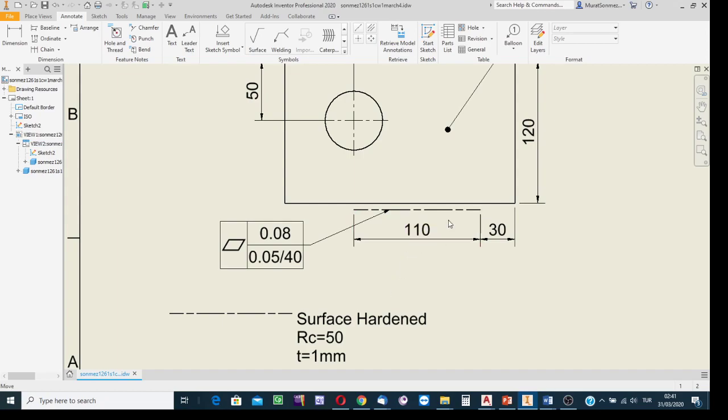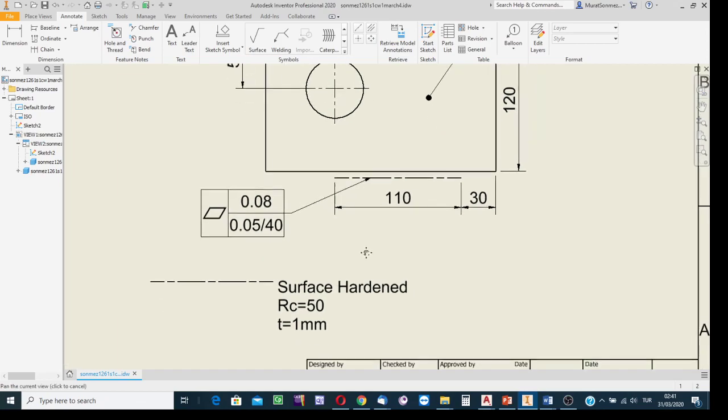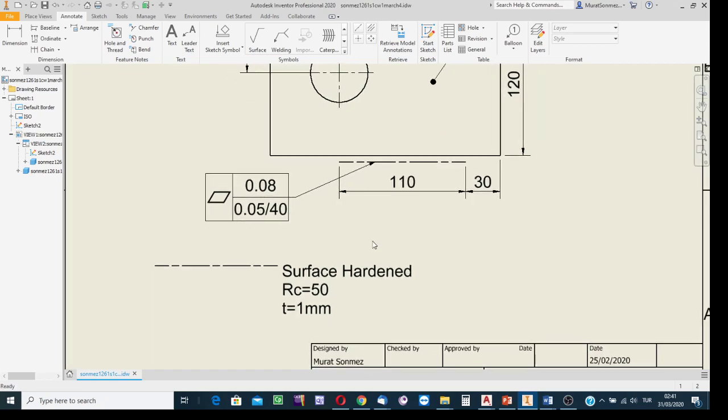In this example, for the same portion of the surface, there is one more requirement to satisfy. But for that requirement, there is no special annotation. If there is no special annotation, then mention the requirement in the form of a text, in the form of a paragraph. For that purpose, the chain line is to be repeated, shown as a piece of straight horizontal line in the vicinity of the projection, similar to a footnote, and the text is to be written.